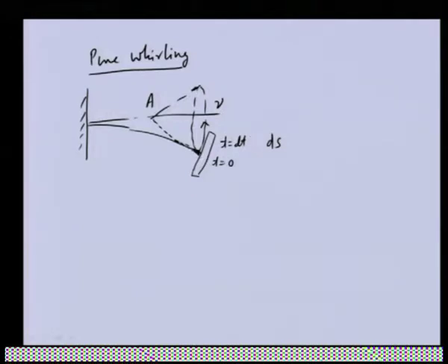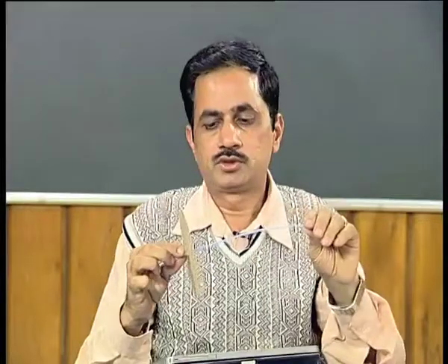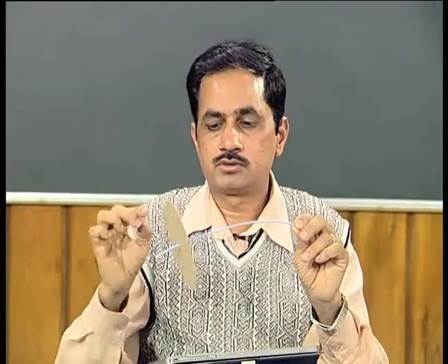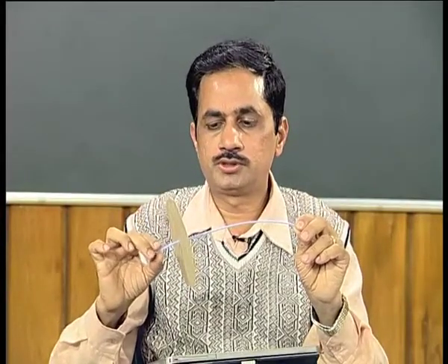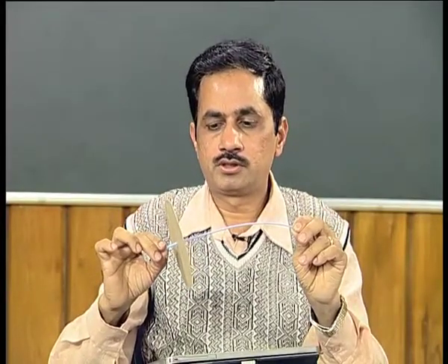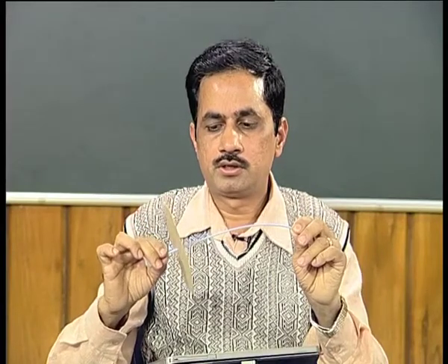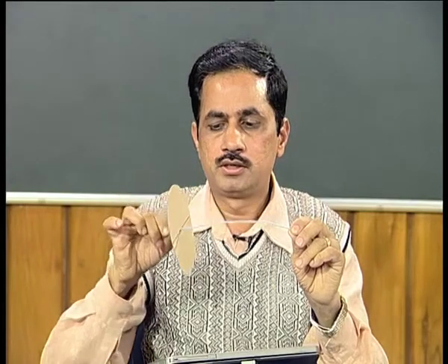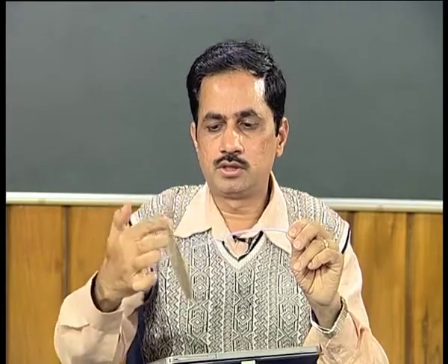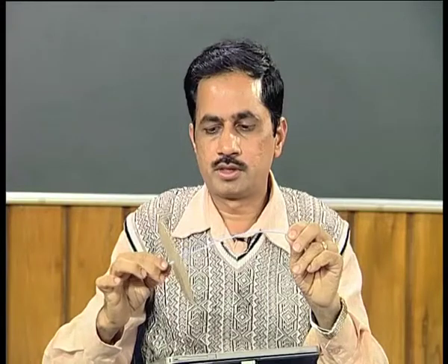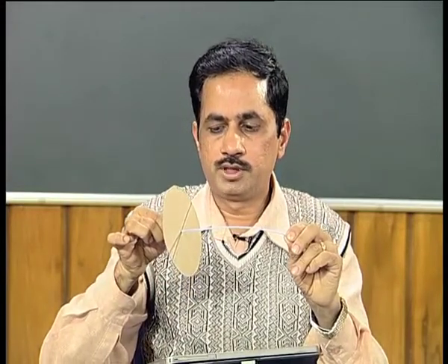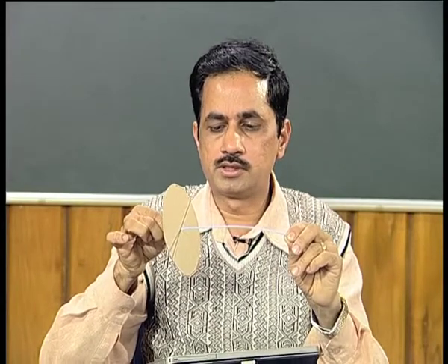Okay. So, in this particular case let us visualize the motion of the disc. It is not spinning, only the whirling we are considering. So, this is at the bottommost position. Now, if I am considering the motion of the disc during whirling, you will see that earlier you could see only a line of the disc, but when it is whirling, when it is inside towards me, you can see the inside face of the disc.